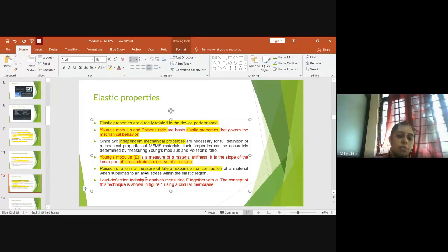Please do consider that when you have a stress strain curve, you have an elastic range and then the plasticity comes on. Once the elastic range has been crossed, the deformation which goes further cannot come back to its original position because it has crossed into plasticity. So what we are speaking about here, with respect to the values, is associated with the elastic region only.